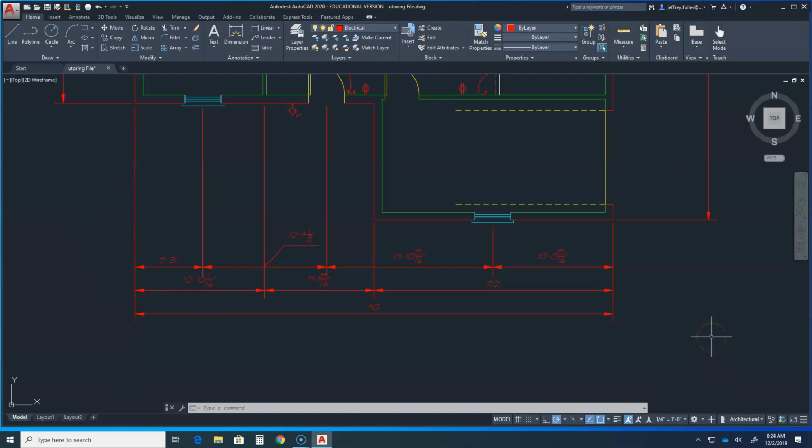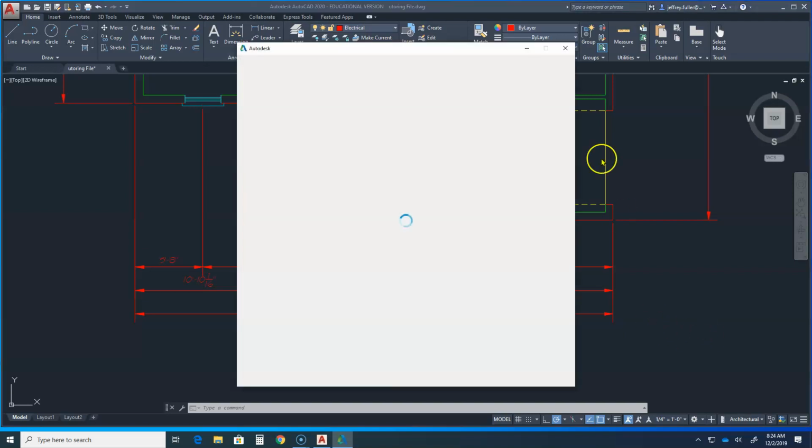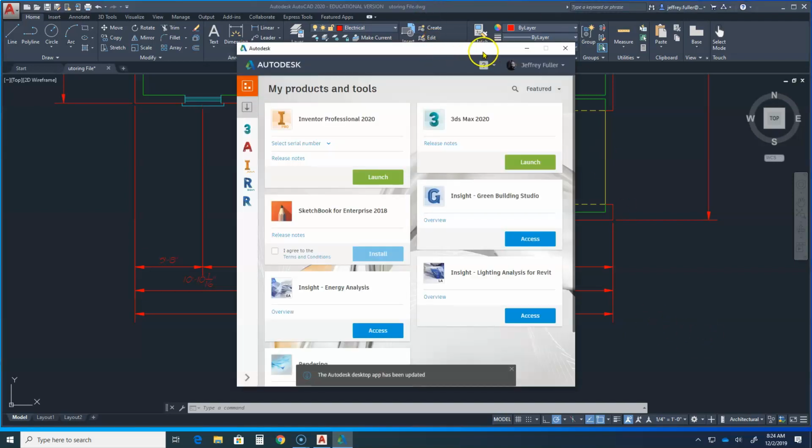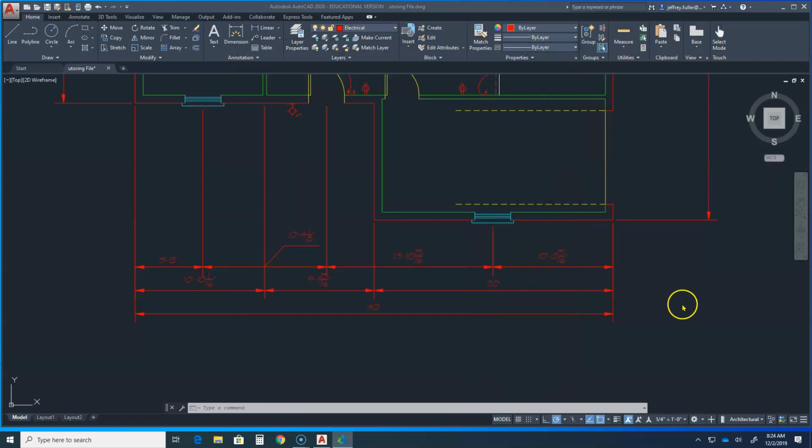Okay, first off is the three dimension lines that we have. But the three dimension lines, you have one dimension line which is 8 feet away from the furthest extent of the building. So you want to use the part of the building that sticks out the furthest to measure the distance of your dimension lines.